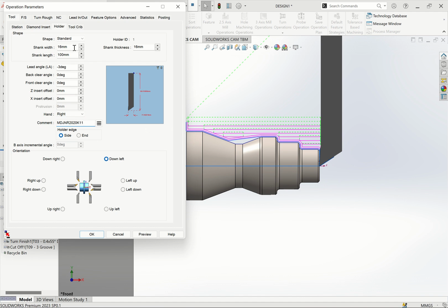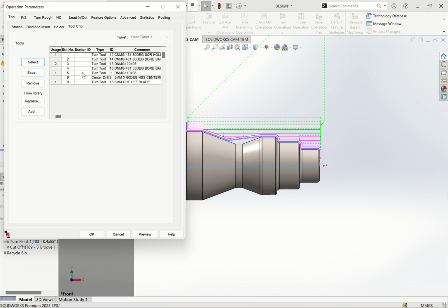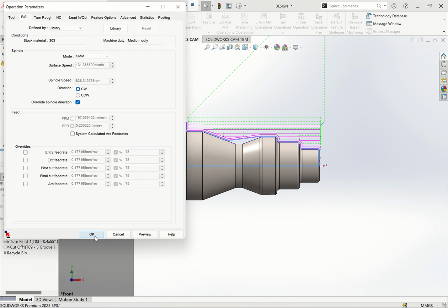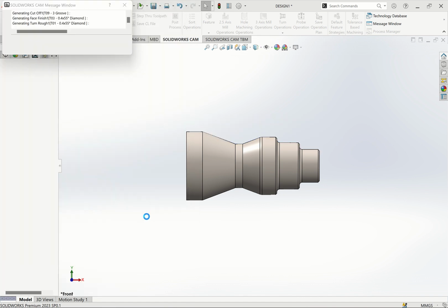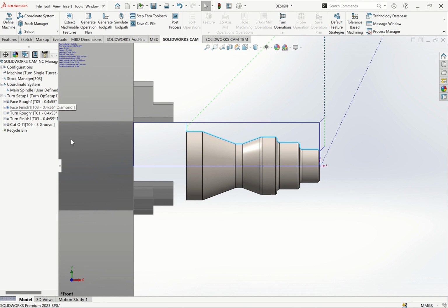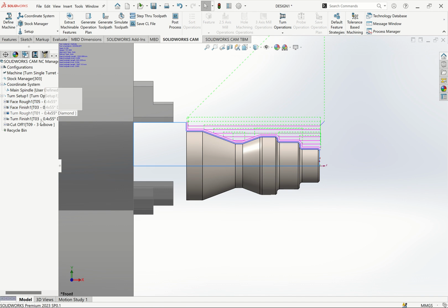This is how you change the tool. I can put here this 20 millimeter. Here, this also, I'm using all these parameters. I'm feeding in the parameters, 125 millimeter. Then tool keep, let it be the way. I can click here. If I click OK, because I've changed that tool, it will ask me to update. Already, it has now picked, because that tool has the same parameter as the previous one that I changed on the face roughing. So this one will now update the tool automatically, and I can now click here, generate toolpath to update